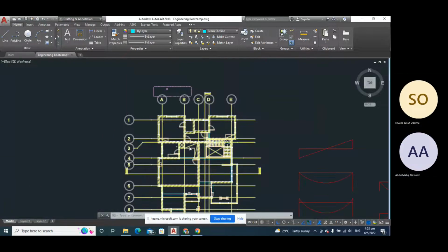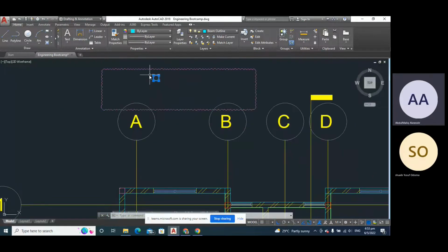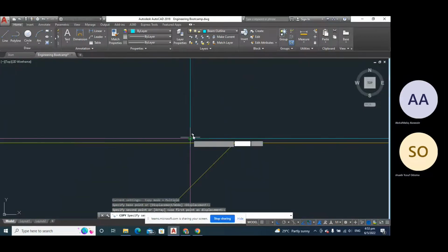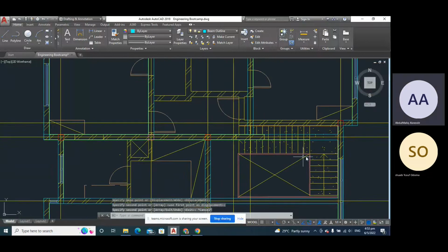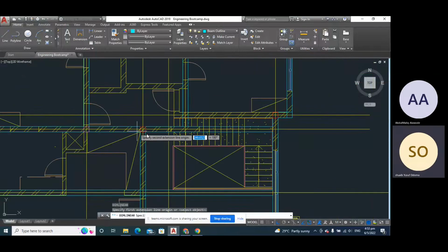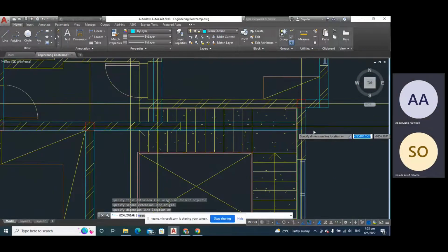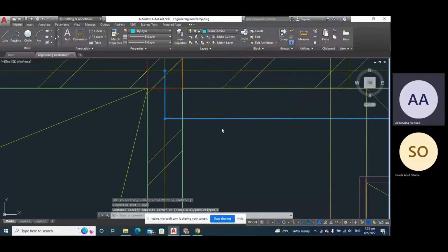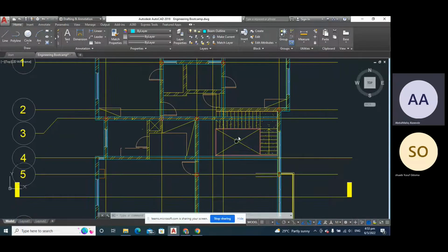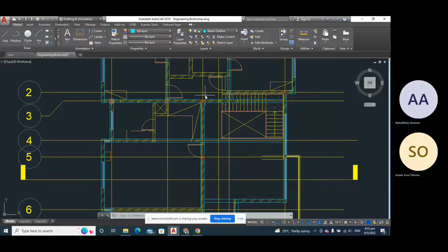To break the span, I can plant another column here. From here to here is what? 5.625, which is fine. So from the whole of this area that I've created, we have enough support there. We have enough columns, and the beams that are supporting beams are perfectly okay.